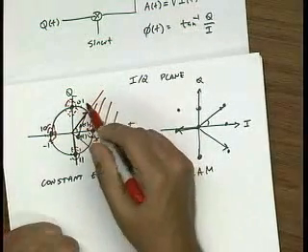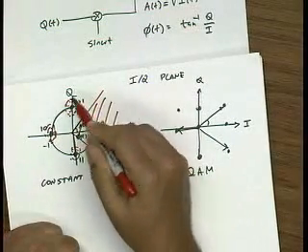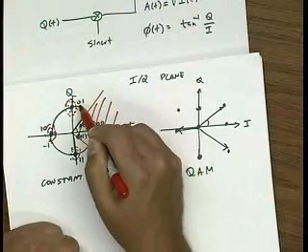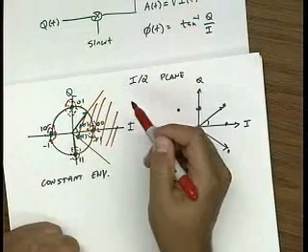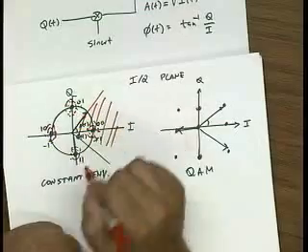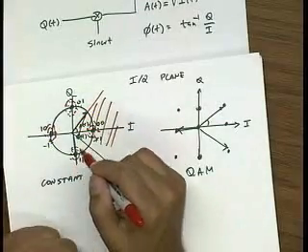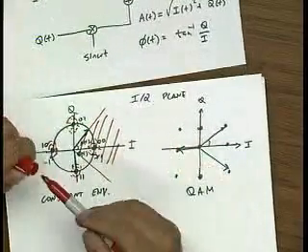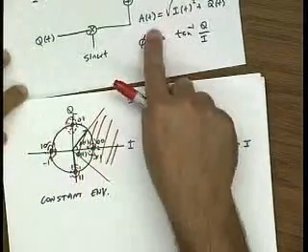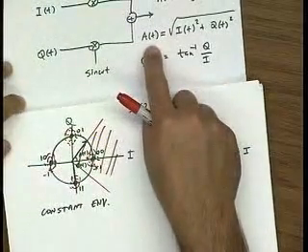If the noise is large enough that it moves you out of this quadrant, then you'll make an error. When you're sending a 0, 0, you in fact receive a 0, 1. So the space between these 2 points is very important. And remember, the space between these 2 points is related to this amplitude, and of course, that's related to the power of the signal.